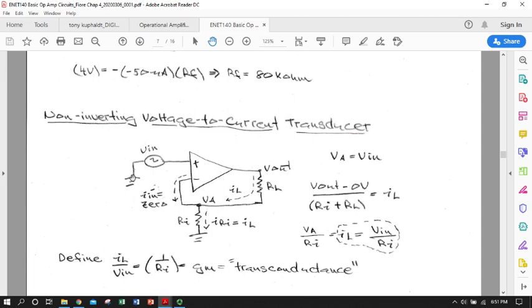Over here, we have what would be considered a series. The input signal is coming into the op amp and it doesn't get a choice. There's no branch. This is not a parallel network. So our signal only has one place it can go, and our output only has one place it can go. So in a way, the load is connected in series to the feedback network. So this is a series combination. And so you can see it's used for voltage to current.